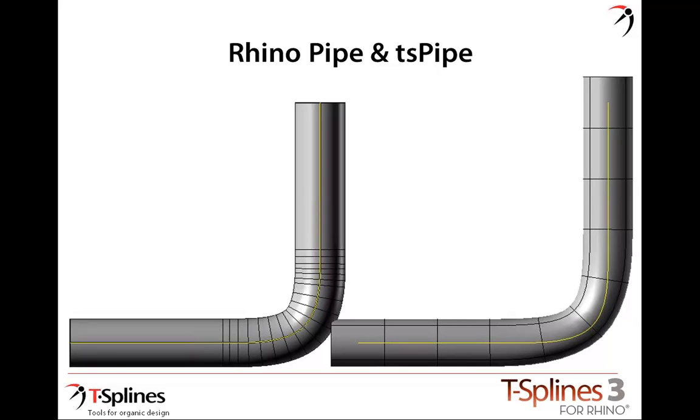And so what that means is that when you've got really long straight sections over here, it'll have very few control points. If you've got high curvature sections, it'll add more control points as necessary. With a T-Splines pipe command, one of our major goals was to make it user editable at the end. And we figure if you want something that's very precise that you're not going to touch again, then the Rhino pipe already exists and does a great job at what it does. So we decided we wouldn't try and reinvent the wheel here.